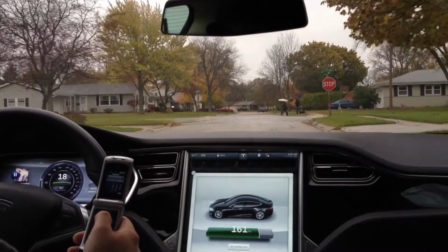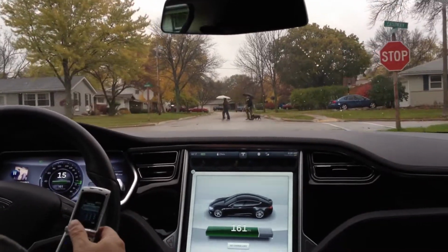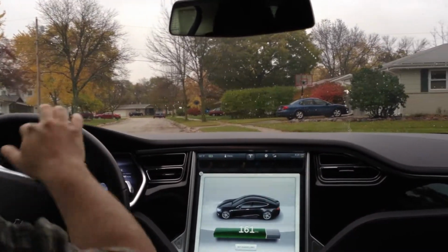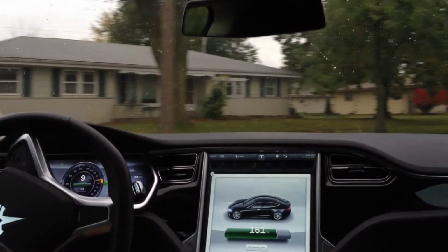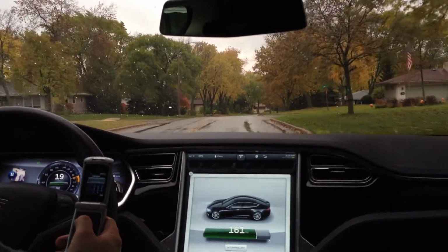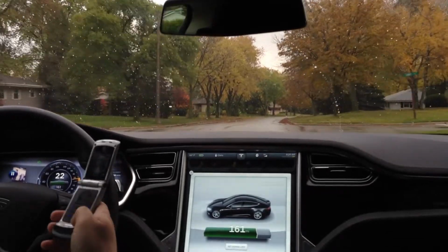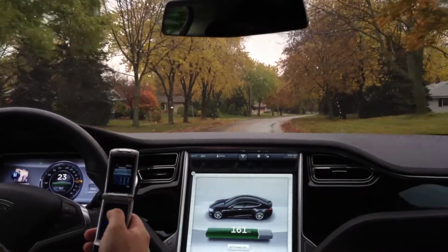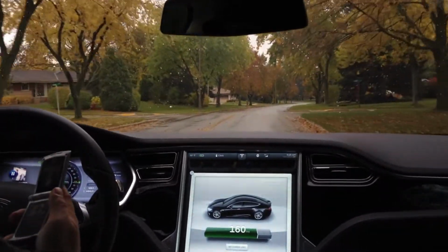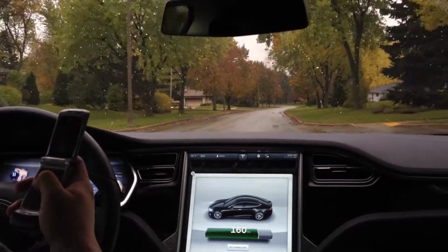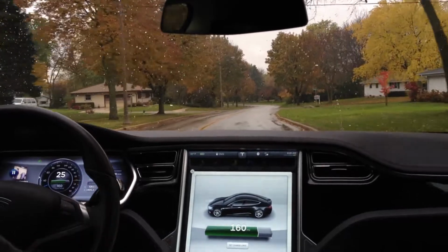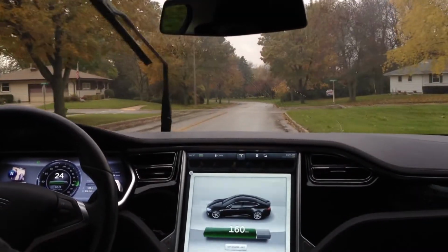I'm actually drawing 9,120 watts. So to find out what I'm getting billed per hour, I take that 9,120 watts times 5 cents, which is 45.6 cents, so rounded up 46 cents per hour instead of 50 cents per hour.